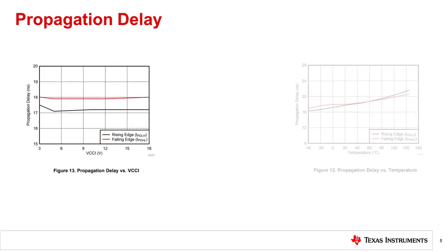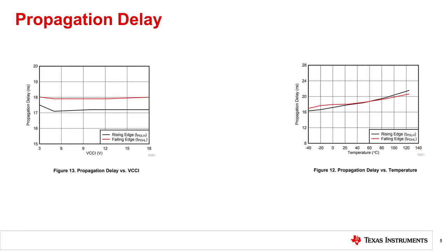Every gate driver will see some variation in propagation delay due to process tolerances, changes in supply voltage, and changes over junction temperature. Careful design removes much of the effect of process tolerances. In an application environment, operating temperature usually remains consistent, and many parts also include internal regulators to maintain stable operating points. Temperature changes usually have the greatest impact on drift and propagation delay.